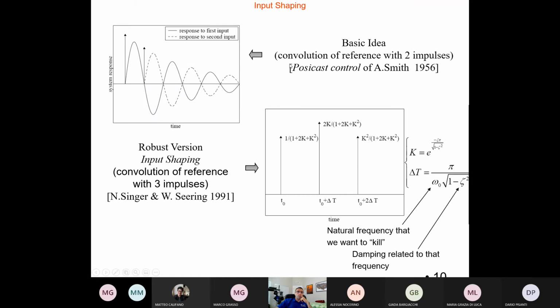The other one that I showed you in the videos, and I have a Simulink file that runs this, is input shaping. Instead of taking the bang-bang and smoothing it like you've seen before, you perform a convolution of the original signal, the bang-bang, so basically a maximum torque, then minimum torque, nothing in between.